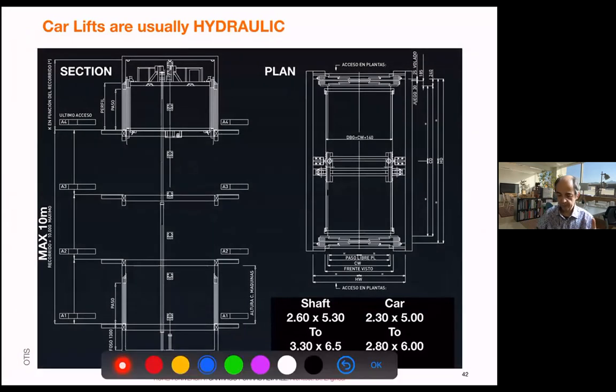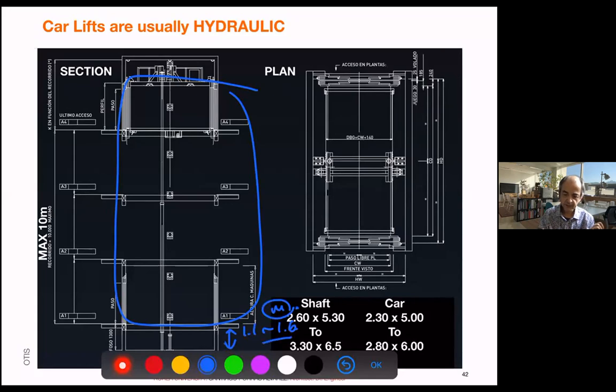I brought some drawings in case you use them. You see, in this case for cars, they give you 4 floors of difference. On elevators, because I saw in your drawings you are a bit confused, you need always a pit, usually 1.1 to 1.5 or 1.6 meters, depends on the elevator, and overhead, which is about the same, 1.1 to 1.6, which is just for safety.